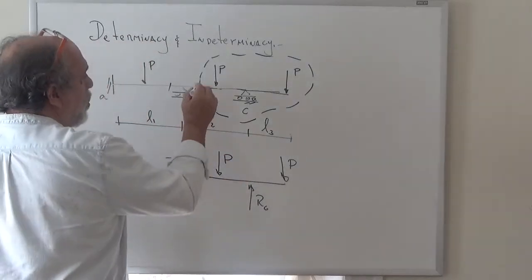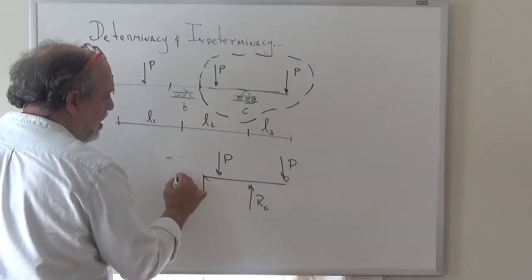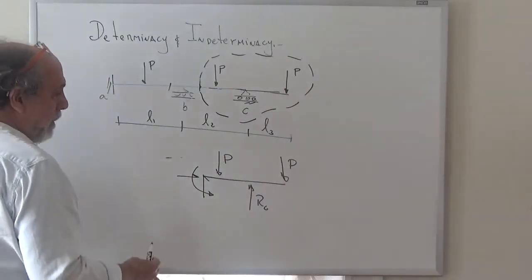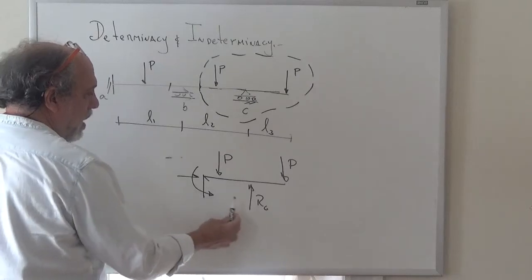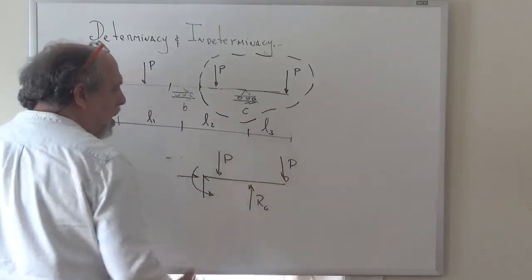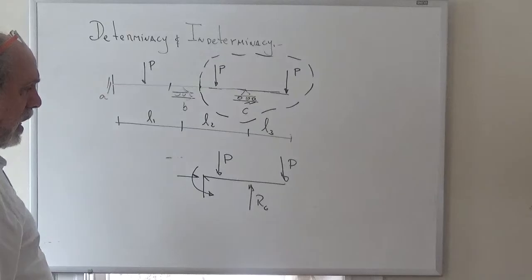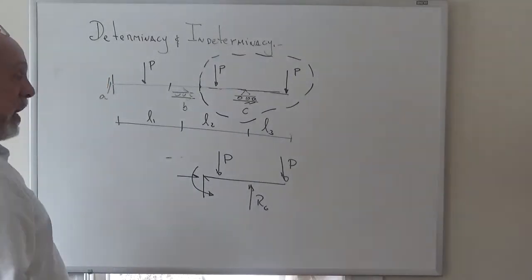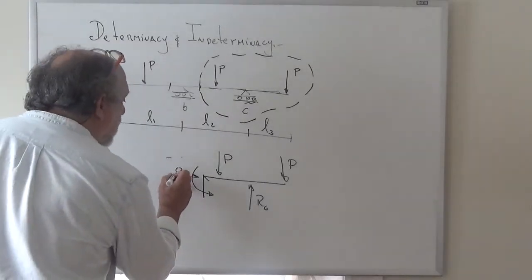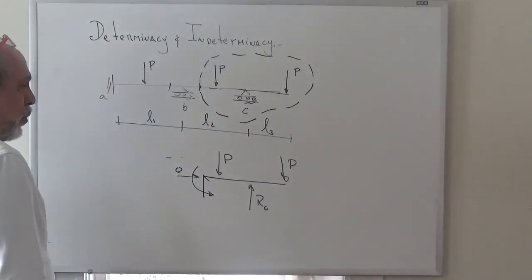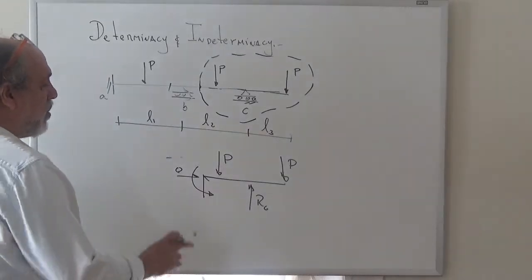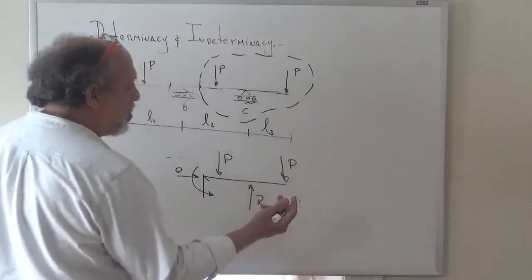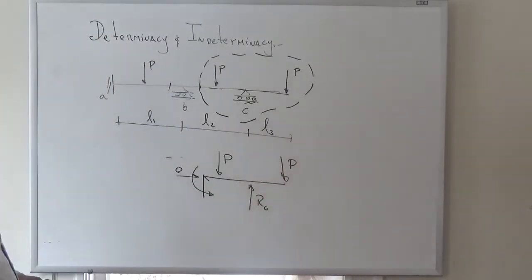Those are not a problem. And then you cut here, right? So here there is a shear, there is an axial, and there is a moment. Now, how many unknowns are there? 1, 2, 3, 4. How many equations of equilibrium do you have in that? You have 3. Therefore, you can't solve for 4 things using 3 equations. Now, again, you could say, but I know this one is 0 from some of the forces in X. True, but you already used one set of equations. Now you have 1, 2, 3 unknowns and only 2 equations. So you can't find that moment. Okay?